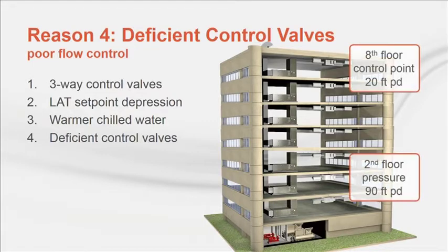In fact, when I arrived, the control valve on the second floor air handler was 100% open because the supply air set point had been set extremely low. In checking, we found out that it was flowing just a little over 3 times the coil design flow at a part load condition. Now, the valves were likely oversized even for the top floor air handler, but they were definitely too large for locations in the system closer to the pumps.